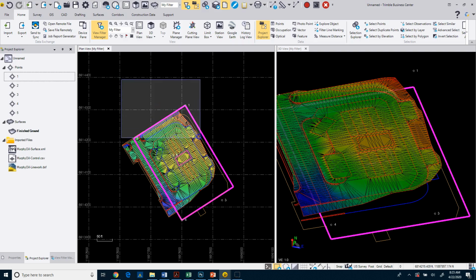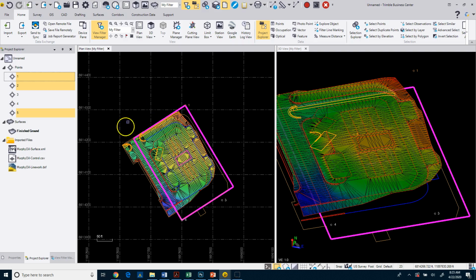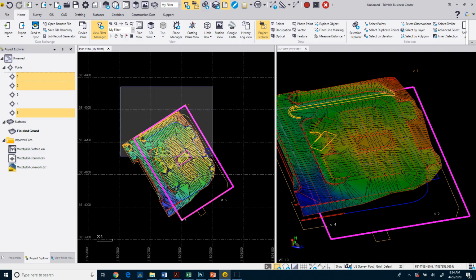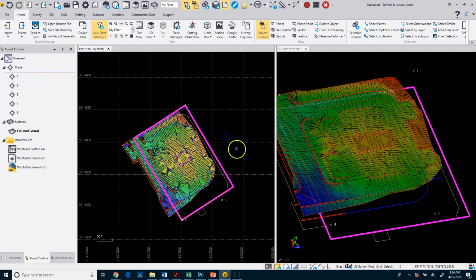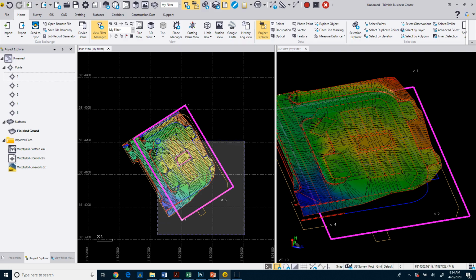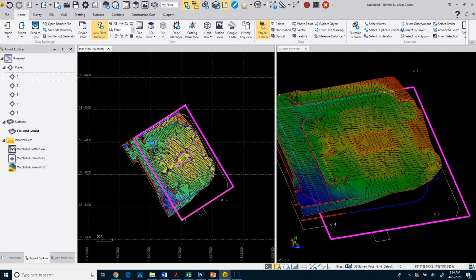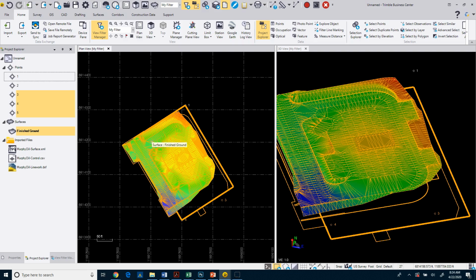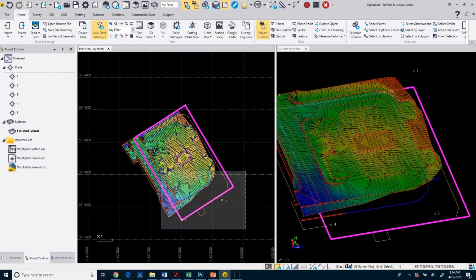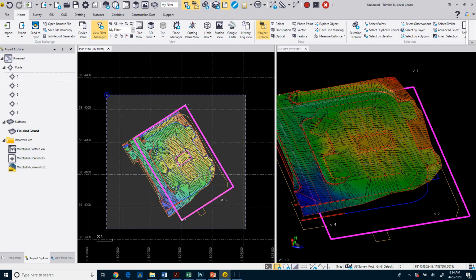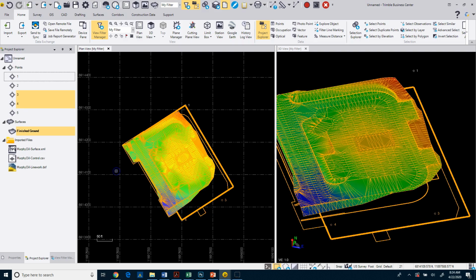Now, if I do that and I only cover a portion of the objects, it's only going to pick up the objects that are completely encased by that rectangle. So this is a window selection. If I go from lower left to upper right and I get this dashed rectangle, what that does is it picks up everything that that rectangle crossed. So you can see that I picked up more information by going in this direction. If I don't completely encompass everything and only do a portion of it, as long as that line crosses that rectangle, then it will be selected.